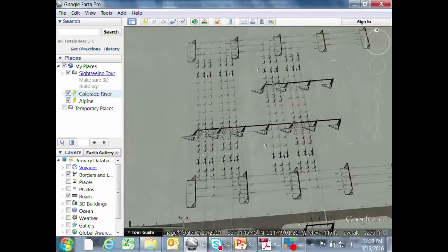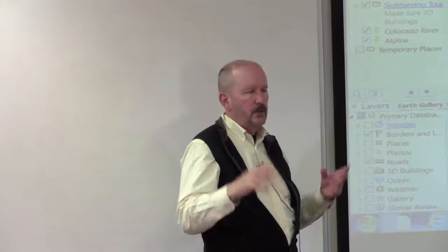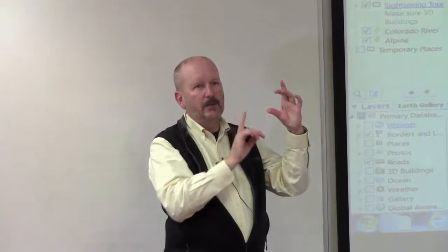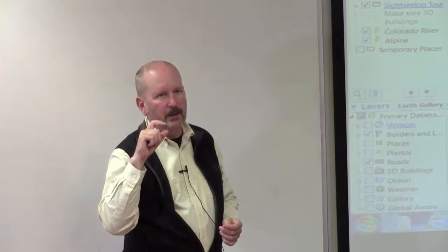And that kind of blew my mind when I first found out about it. In fact, I first found out about this not from this particular situation, but from an old substation over on Johnson Creek. I think it's called Johnson Creek Substation. It's an old box structure that was designed to fit into an oddly shaped piece of land for the substation. With this box structure, if you didn't need a bay, you didn't have to put the leg in. Well, we needed to add a bay to the structure, and so we just ordered another one of the legs, but it was going to go under a beam that was already spanning over that. None of us even thought about it, that beam was deflected about 1.5 inches.